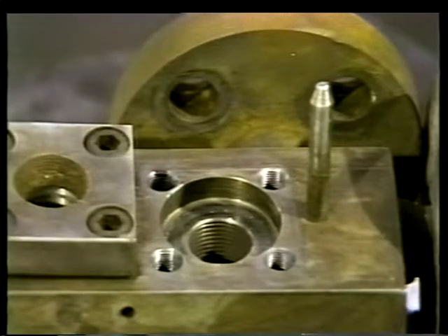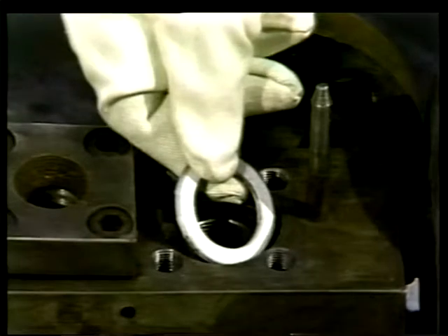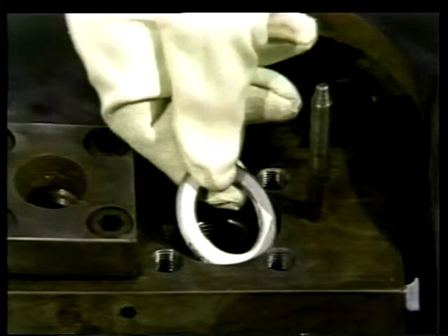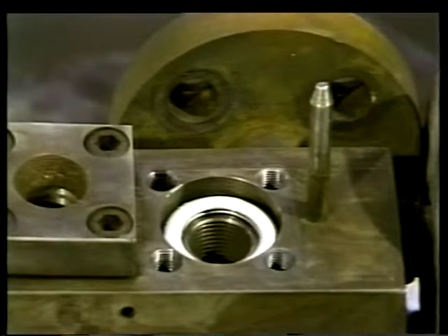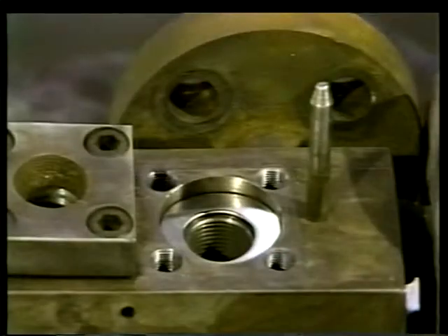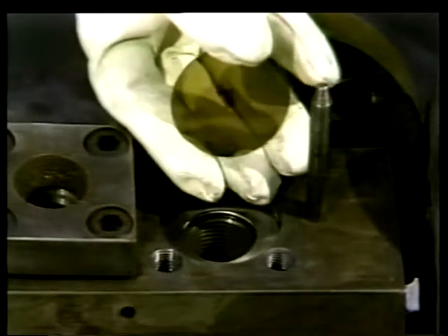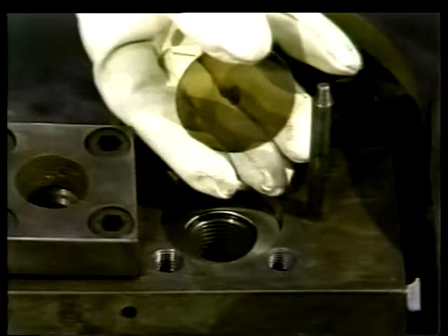Place the sealing gasket in the gauge. Do not use Molykote or other types of lubricants on this type of gasket. Next, place the protective gasket and then the mica into the gauge body. The mica may be marked with a red dot. Place the red dot side towards the pressure side of the gauge. Handle the mica by its edges, but avoid bending it.